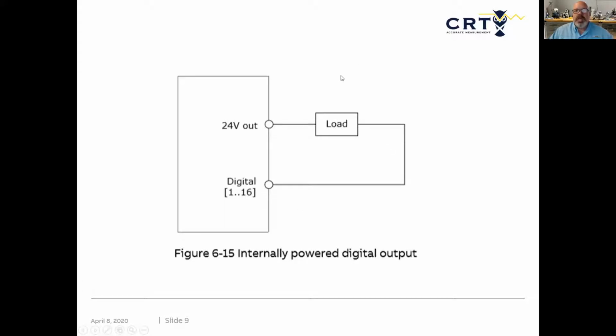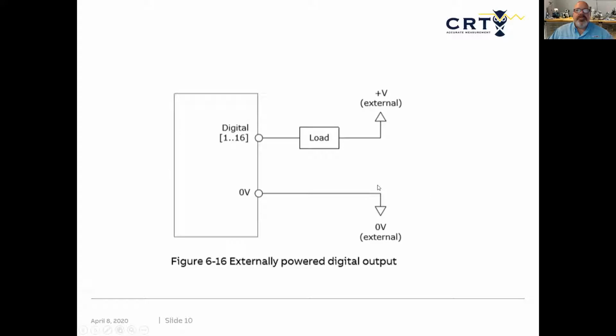So again, if I'm wiring in a relay, I can go either externally or internally with my 24 volts to that load, and then I'll switch it on the common when I come into my digital input. So wiring, again, on the XS, I still will go into X1A TB3, and that's digital input number 1, or digital 1, and I'll switch it here. And all of these figures, again, are inside the manuals. This is using an external supply, so I'm bringing 24 volts out. You can see I come into my digitals 1 through whatever, and then I've referenced that power supply 0 volts with my voltage.